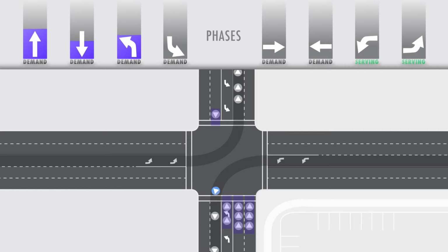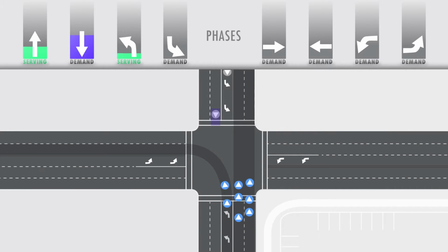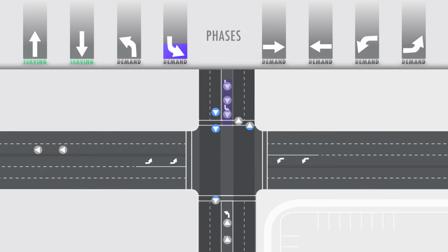As soon as the east and westbound lefts clear, InSync now sees the northbound through and northbound left have the highest demand and serves them. The north left finishes, but InSync sees that the north through just needs a few more seconds so the cars can pass safely through. So, InSync gives green time to the southbound through while continuing the northbound through. As soon as the northbound through finishes, InSync serves the southbound left phase. As the southbound through phase clears, InSync calculates the demand of the northbound left and sees that it has enough time to reserve that phase before the tunnel is served again.